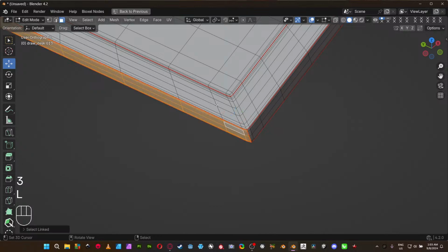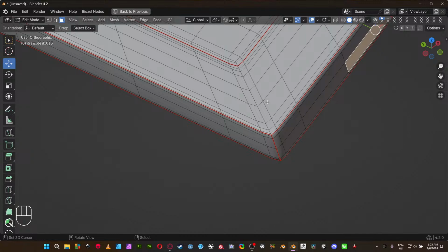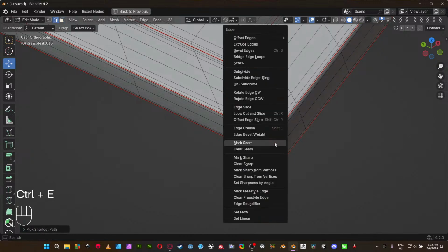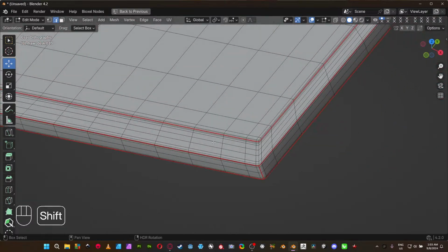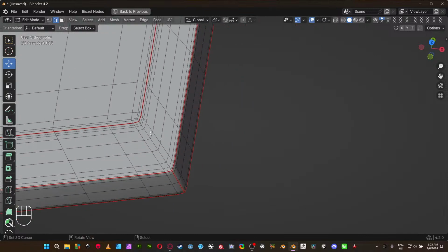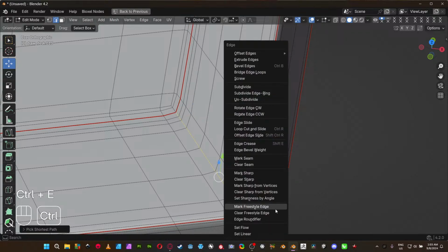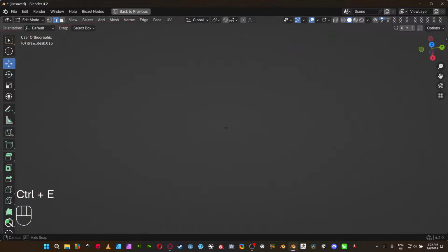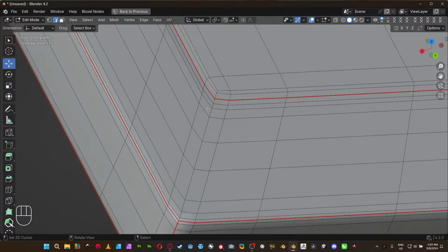Like this guy, we can merge it with this guy, and then we can optimize spaces with the UVs. So this is a pretty good technique. It's a basic technique, but at the same time it's something that beginners don't take in mind because they say, oh, I didn't think about something pretty easy that is gonna make my life easier. So let's just make a cut in there, just in the top, because in the bottom we don't have any gaps. Let's just make something like this.